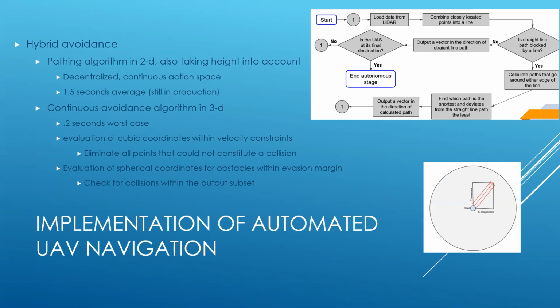Assuming that the path is blocked, however, the algorithm will plot safety bubbles around the edges of each of the obstacles. The line tangent to the safety bubble is considered the most efficient travel path for the drone to navigate around that obstacle and towards the target. So these tangent lines are considered to be the set of possible paths. The path that is determined to score the highest is used to determine the next waypoint at the tangent point.